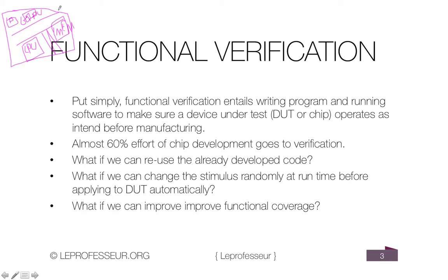Think about it, to verify this whole system is a very complex task. And if your bus is 64-bit, how can we make sure that every combination has been exercised? So it makes more sense if our input stimulus to the chip or the IP under verification has a random pattern. We can maximize our coverage.